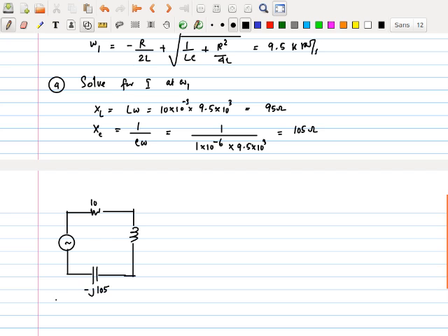Remember, a capacitive reactance is minus of XC. Then that is J times 95. If you are interested, you can also convert this into R theta type of format, and this is going to be equal to 105 with an angle of minus 90 degrees, right? And this is equal to 10 volts at 0 degrees. So you realize, if I give you the frequency, you can convert this into an AC circuit.